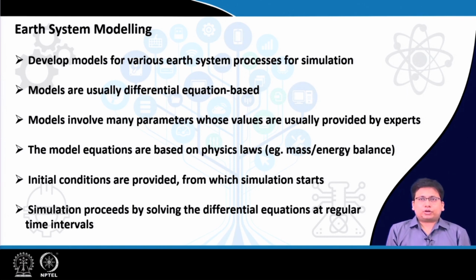That is of course a toy model, as I said, but the actual models for the different processes also have governing equations which express the time derivatives of the different variables in terms of each other and so on. Most of these model equations are based on some laws of physics, say for example, conservation of mass, conservation of energy and so on. Whenever we want to do any kind of simulation by these models, the initial conditions are provided from which the simulation starts. Then this simulation proceeds by solving the differential equations at regular time intervals.